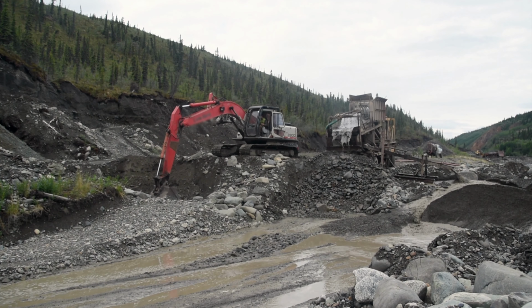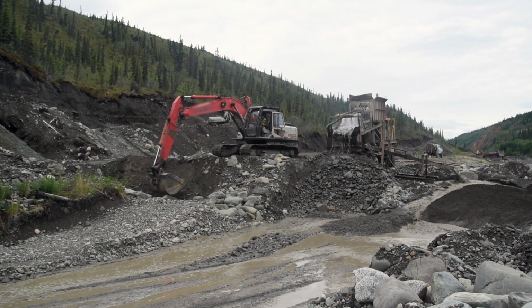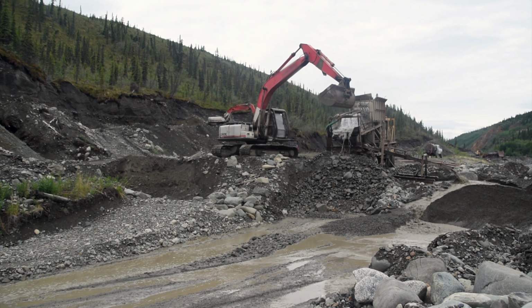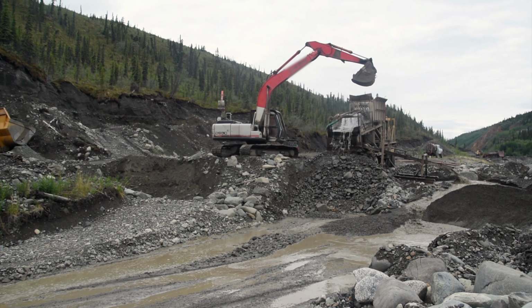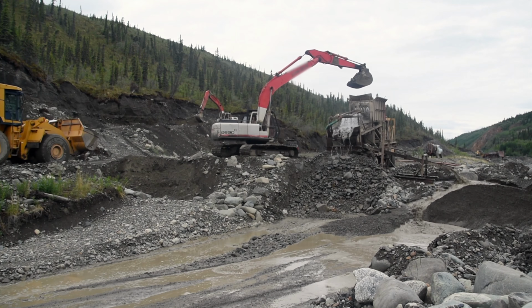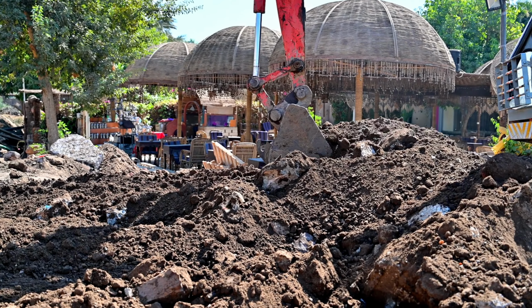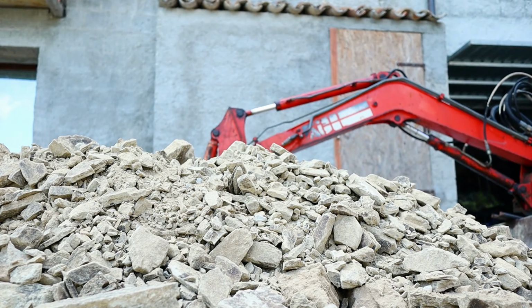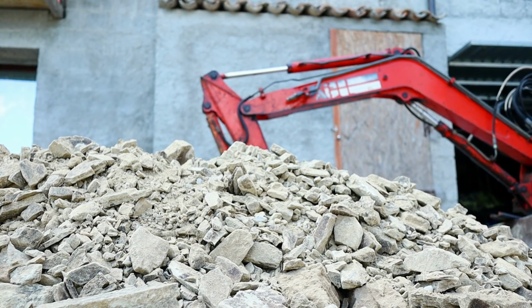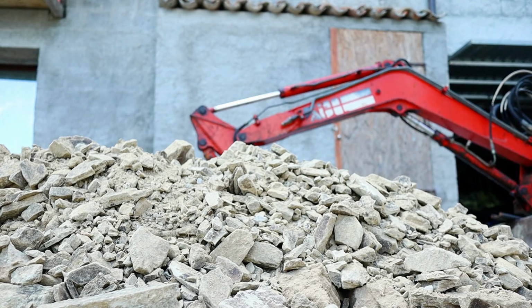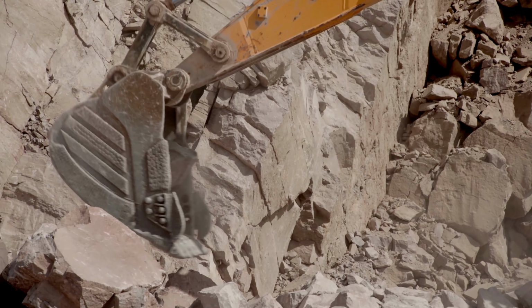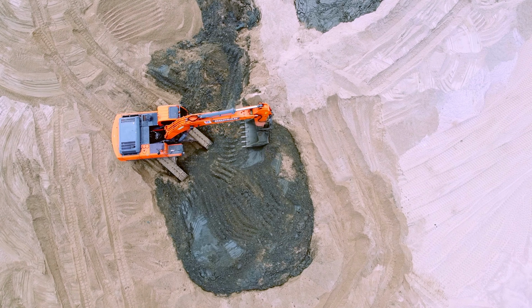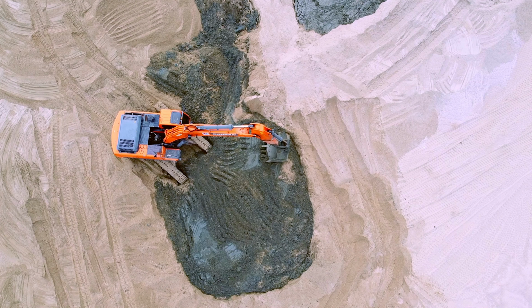Modern excavator booms and arms are therefore designed with smooth load paths, optimized cross-sectional geometries, and reinforced high-stress regions. Weld joints are carefully designed and positioned to minimize stress concentrations, and advanced welding techniques are used to improve fatigue strength. In addition, manufacturers often use high-strength, low-alloy steels, which provide greater strength and fatigue resistance while maintaining reasonable weight. Through these advanced design practices and analyses, engineers ensure that excavator structures can safely withstand millions of loading cycles during their service life, allowing the machines to operate reliably even under harsh and demanding excavation conditions.